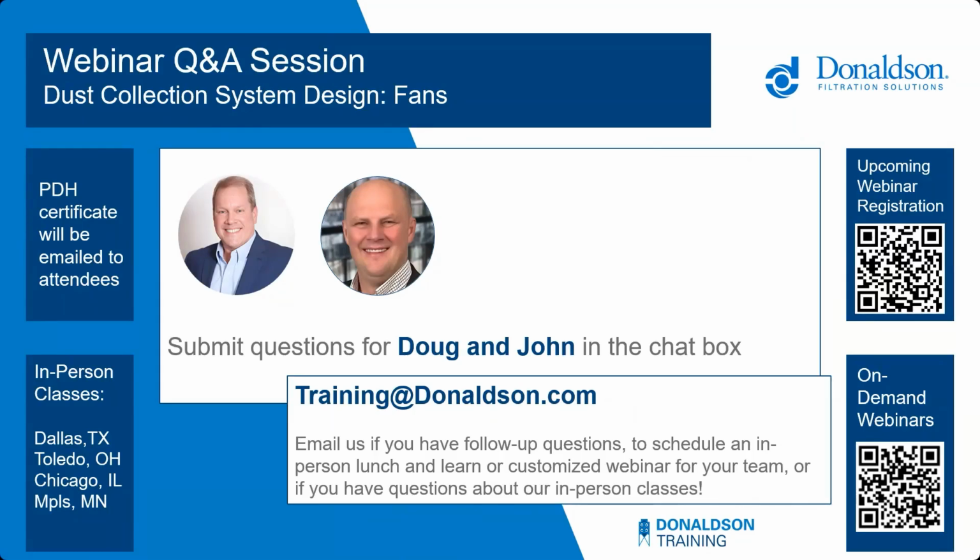Thank you, Doug. All right, next question. How much does a fan silencer reduce the sound level? A silencer is designed specifically for the sound frequencies that the fan produces. And that selection software that we were looking at will give you that information. And then adjacent to the fan selection software is a silencer selection program. The silencer selection program will take all those sound frequencies and their levels and design the silencer to attenuate the sound level to whatever you decide.